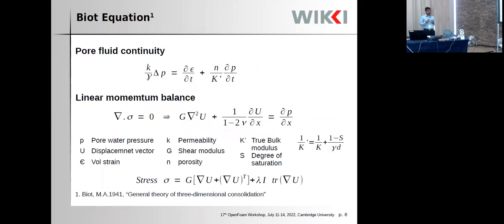So here are the Biot equations. These are the equations for representing the poroelastic solid. There can be many different equations, but we wanted to have it very simple, because in the end we wanted to compare against the experimental results, and if we have a complex model, we would have a large number of parameters, and it is very difficult to determine them from the experiments. So here we have two different equations.